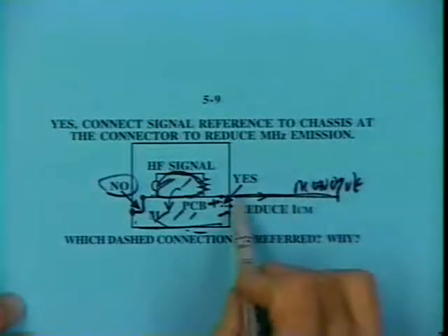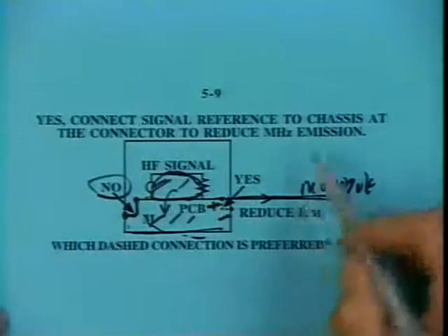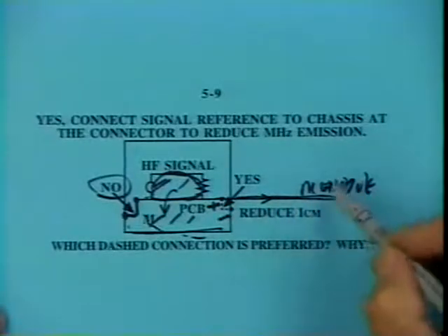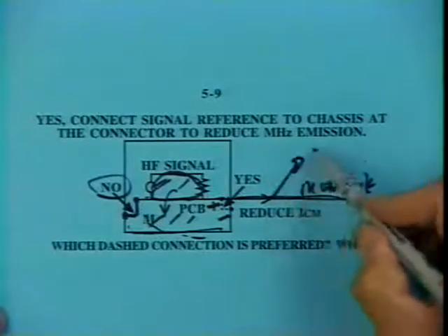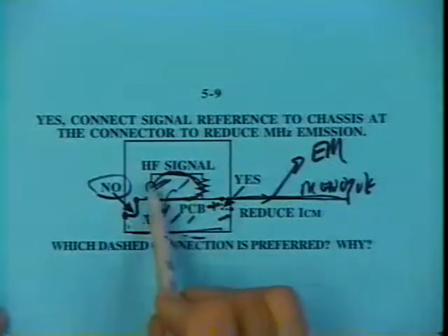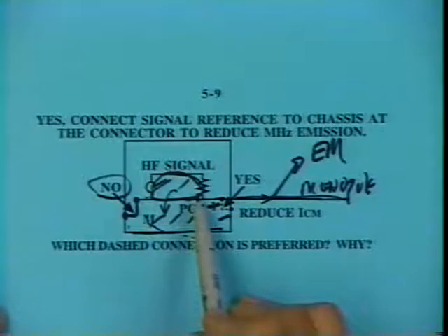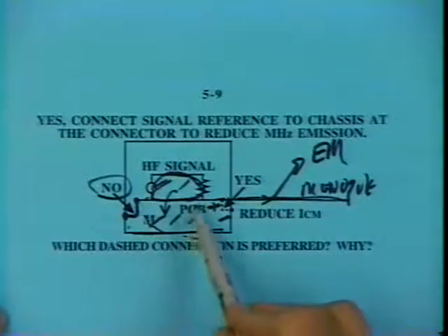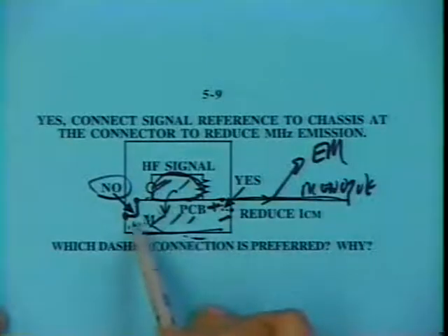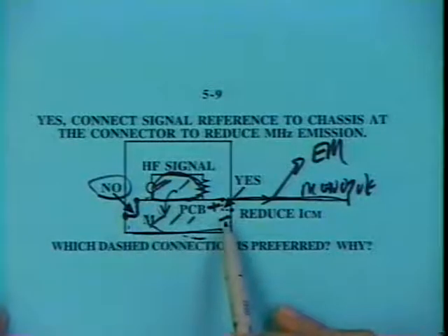And we'll have common mode current coming out on this antenna. What's supposed to be a non-radiating cable actually turns out to be a radiating cable, and we'll get electromagnetic emission coming off of that wiring. So we talked before about how sometimes we have high-speed digital circuits unintentionally coupled to an antenna. In this case, the unintentional coupling is due to a mutual inductance that occurs internally within this box.